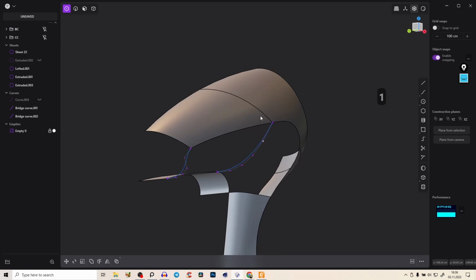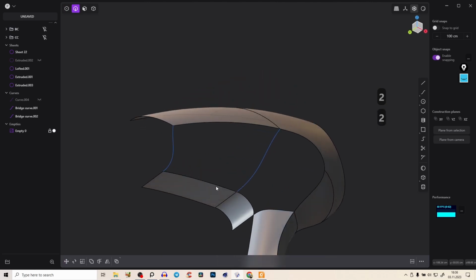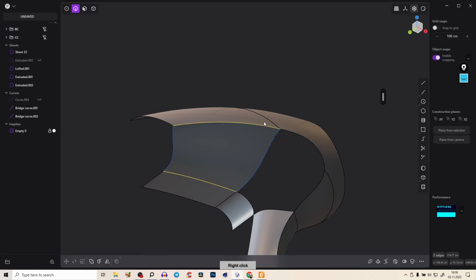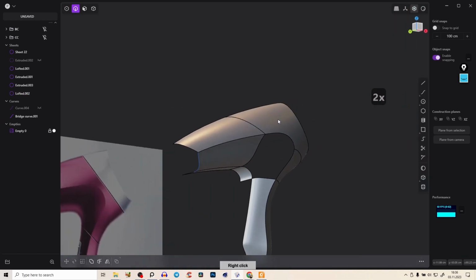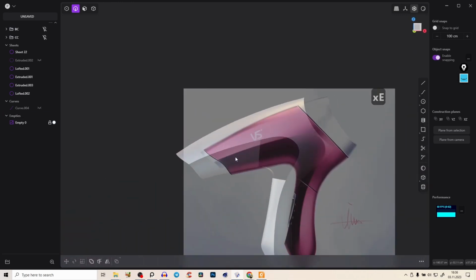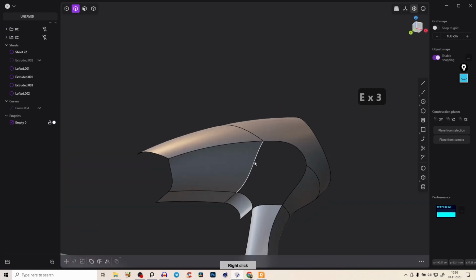And the same here, just select this last point because here we want a nice curvature and drag that up a little bit. And now magic, loft, Shift, G1 we need and G0 here. Press OK. And now guys, you see, we have exactly what we want. And here you see we are getting a dark shadow, so really beautiful.